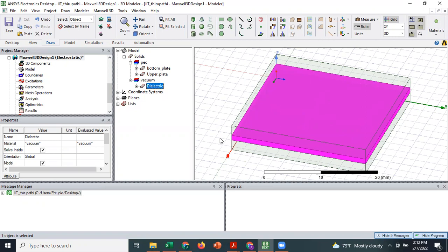And for 3D, you don't have to use a boundary condition because it is already a 3D geometry, right? So you don't need a boundary condition here, unless you need, say, an insulating boundary between some conductor or some area which is going to conduct. In that condition you can have an insulating boundary, but other than that, usually in 2D we used to give a boundary condition in the regions, right? It is not needed in this 3D design, so we can skip that.